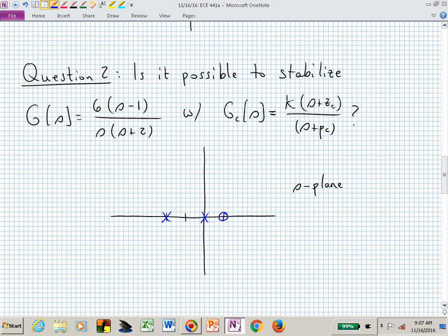So now, is this a case for the phase lead or phase lag? Now you know this system is unstable if you just used a gain controller. Now you want to be a little bit more broadly thinking or more creative thinking in terms of where I put my poles and zeros. You may not want to be stuck in thinking, oh, it has to be a phase lead, oh, it has to be a phase lag. Just open up your thinking process and say, I just need to be able to stabilize this system.